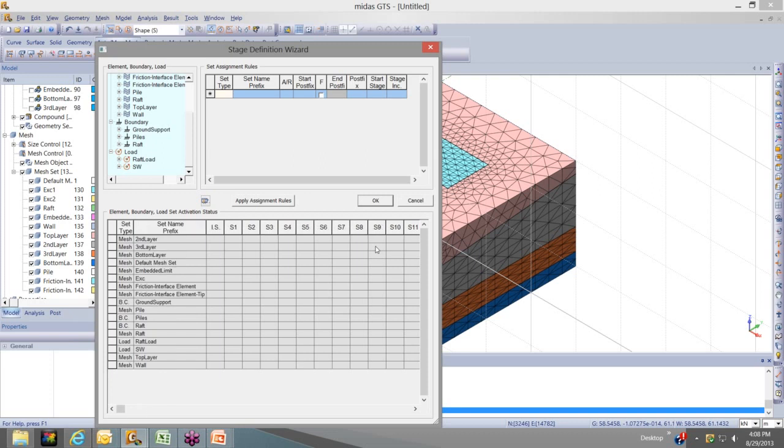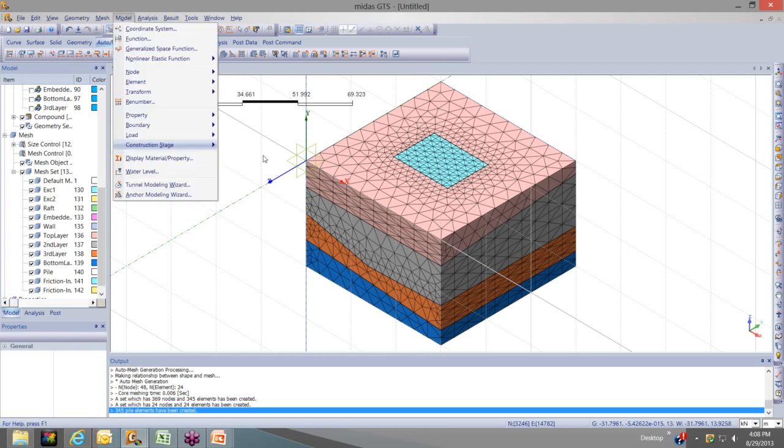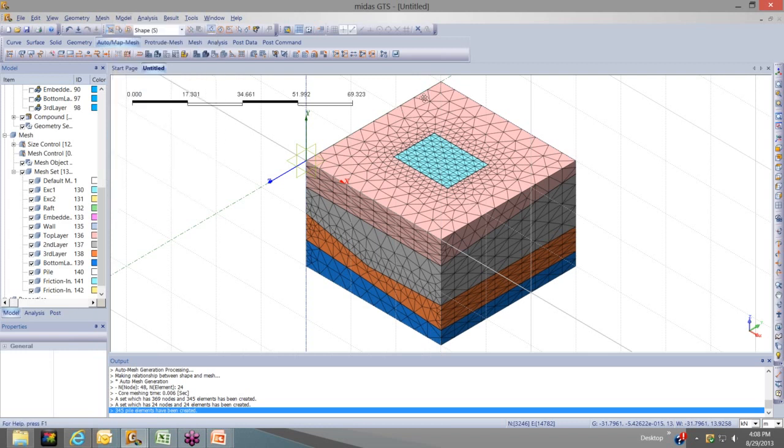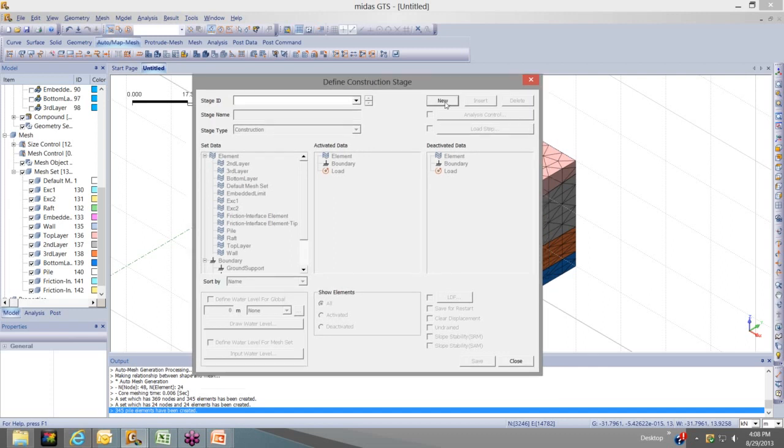If many of you have a higher-end project that you're working on where you'd need this sort of interface, we'll talk. We can set up a private or customized session. But since this is a very specific, higher-end option, we'll just use a simpler construction stage analysis tool for now, just Define Construction Stage, which is for smaller scale projects such as this and is much more commonly used. So what you need to do is just go to Define Construction Stage and then select New.